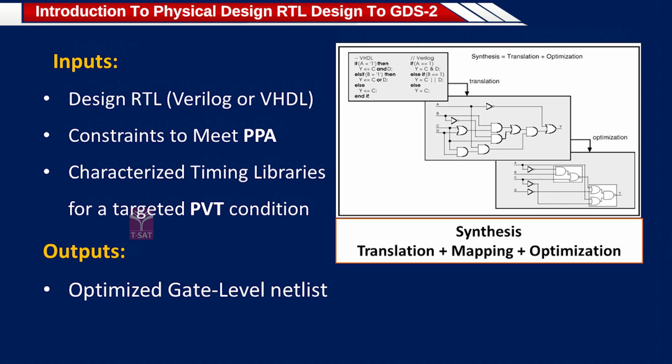That is called logic optimization or logic restructuring. These logic synthesis tools are able to do that. By looking at the constraints after mapping, if any violations are present and you are not able to meet the design targets, the tool will go for logic restructuring to meet those constraints. That is called logic restructuring: realize the same functionality with a minimal number of gates.